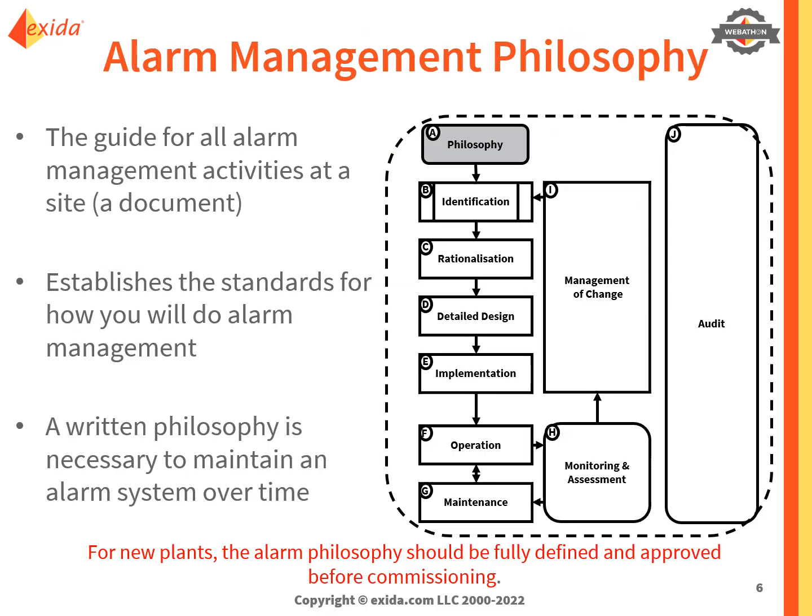The first step to constructing a master alarm database is understanding what our philosophy will be towards alarms. And we do that by constructing another document called the Alarm Philosophy Document. This document establishes the standards for how your company or your site will address all aspects of alarm management, including design, operations, and maintenance.